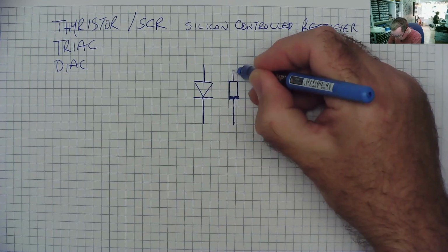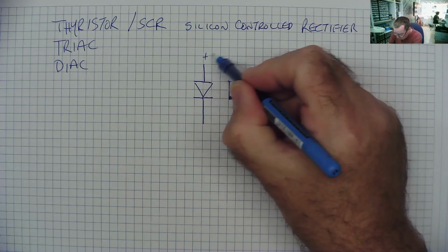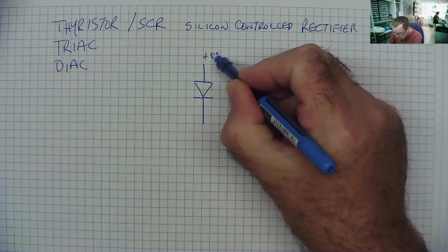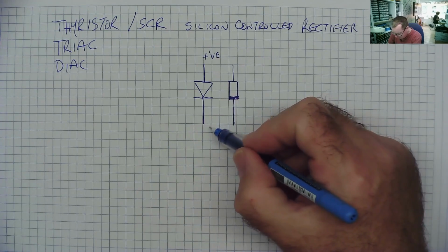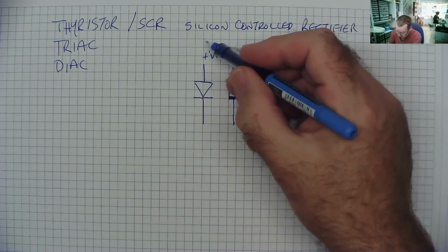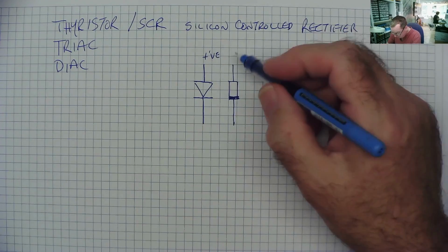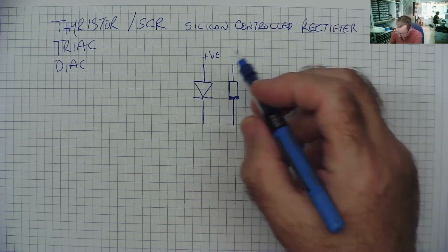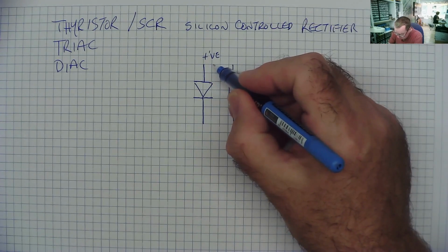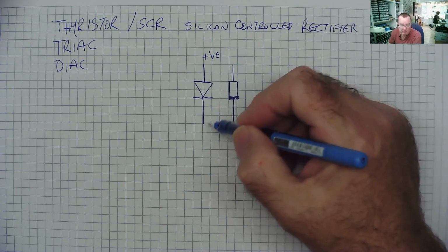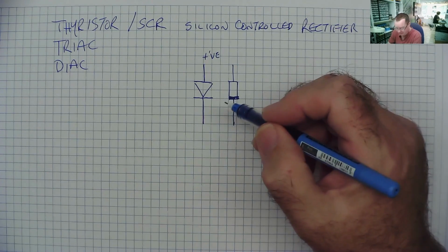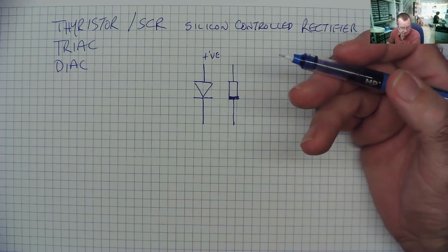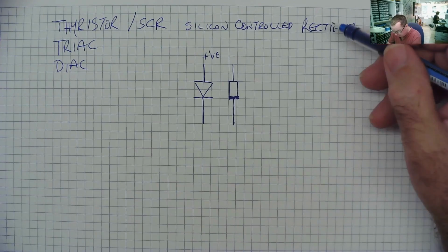So that is our diode. And if we put a positive voltage on this end relative to this end, so if you like plus and naught or plus and minus, current will flow. And when the current is flowing, it drops about half a volt. We've seen that with the multimeter in diode mode. That's what a multimeter in diode mode shows you, the voltage drop.